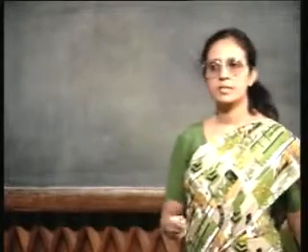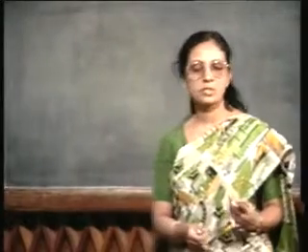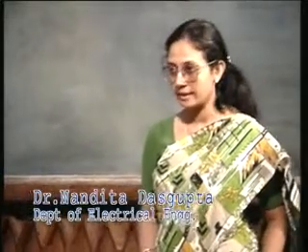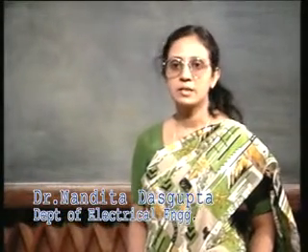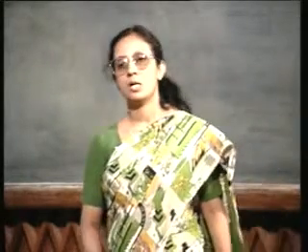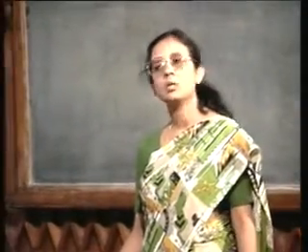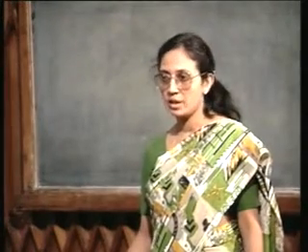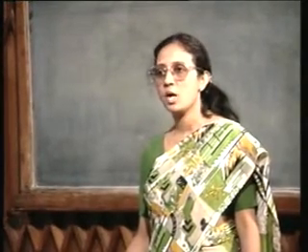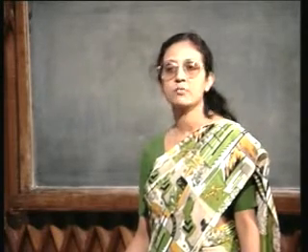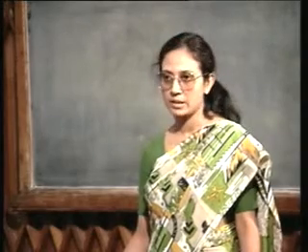So, we have been discussing the different processing steps used in fabricating a bipolar junction transistor in an integrated circuit. We have started with an NPN transistor. We have seen how the isolation between the transistors has to be obtained either by junction isolation or by dielectric isolation. In dielectric isolation, you have also seen low cost as well as trench isolation, and then we have said that it can even be done by using selective epitaxy.